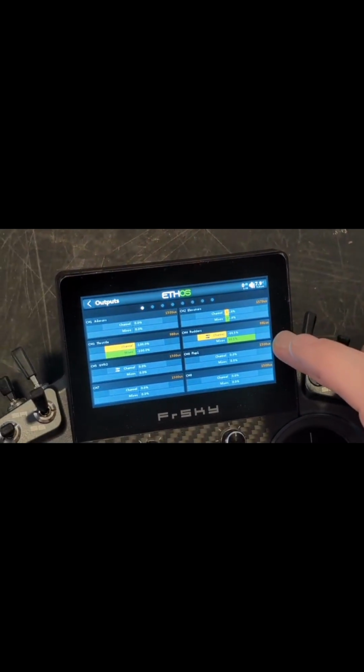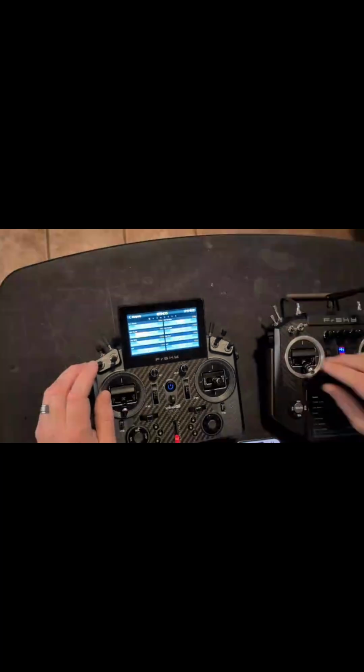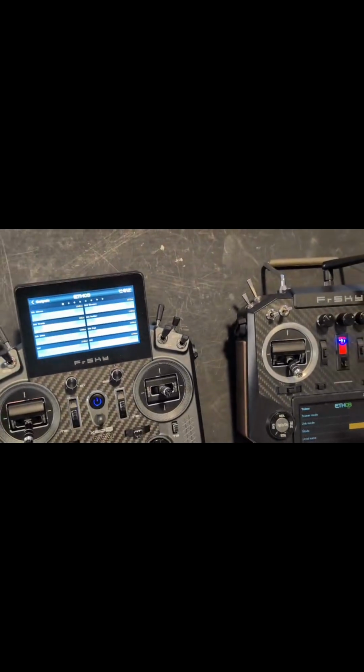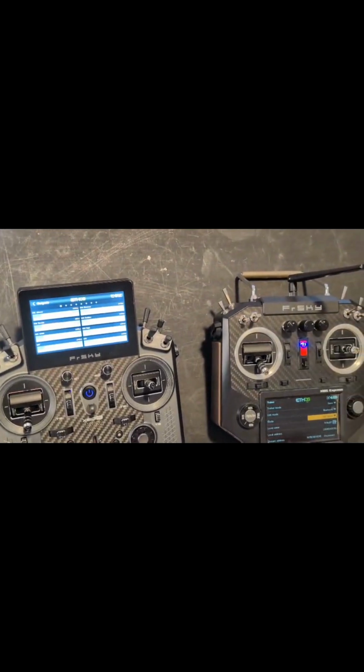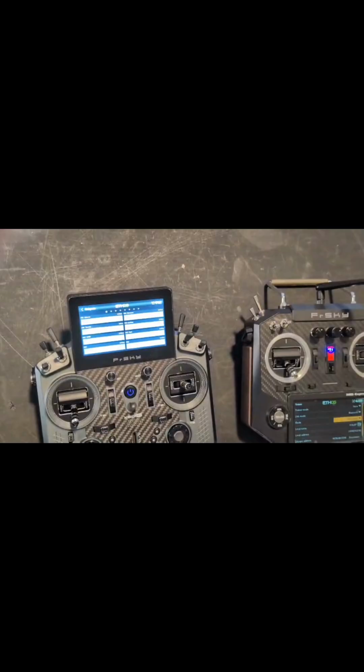We'll check the rudder. Okay, so you can see here that it's reversed. So we want to see the same behavior when we give the student control, left and right. You can also do this with the throttle, but on this instructor radio, the throttle safety switch is on, so you can see the throttle's not working at all. The other way to verify this would be to plug the airplane in and verify the controls moving the sticks as we just did.